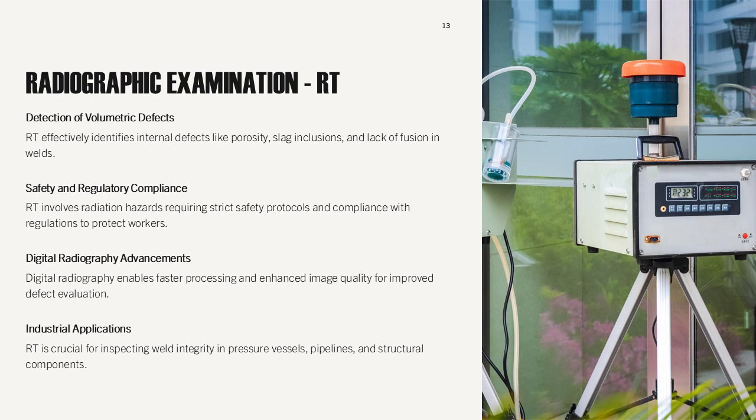RT provides a permanent record of inspection and allows precise evaluation of defect size and location. However, RT involves radiation hazards, requiring strict safety measures and qualified personnel. Limitations include high cost, time consumption, and difficulty in detecting planar defects.